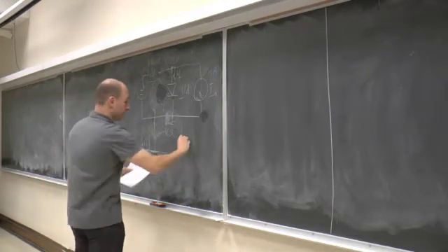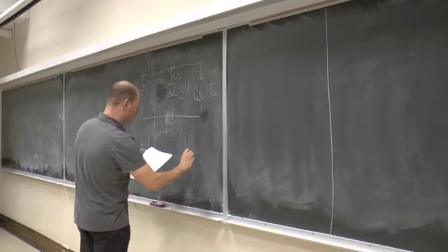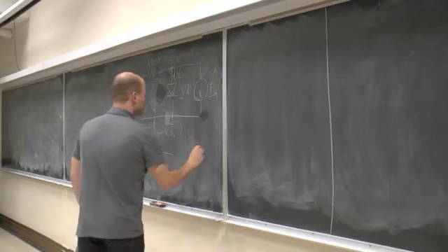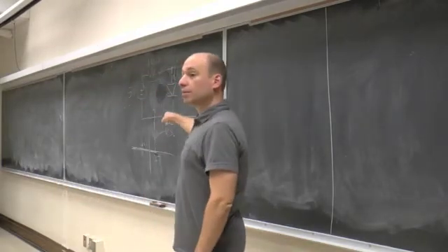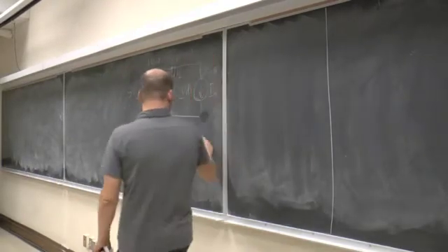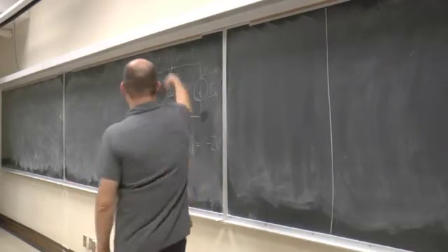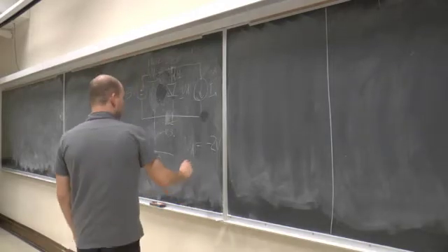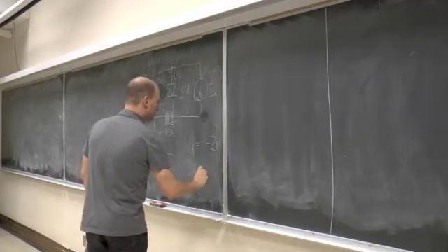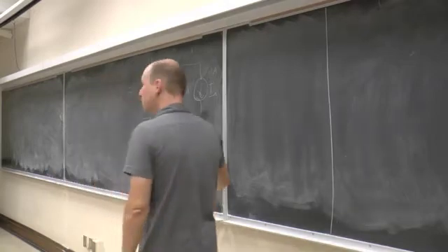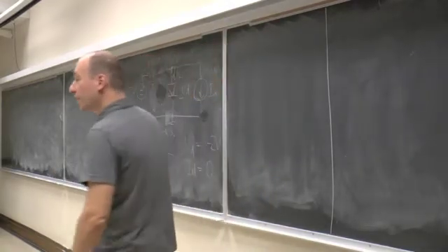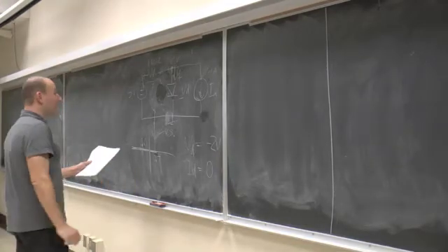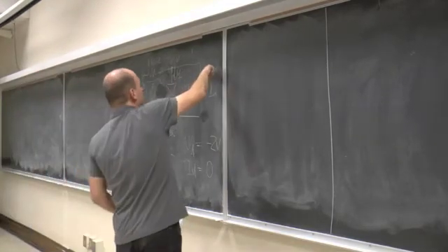Okay, so what's diode voltage? What's the voltage across the diode? That's what's being asked. -2 volts. And what's the current through the diode? Voltage across, current through. The current through the diode is indeed 0. We don't need to give units to the 0, but we can. Okay? All right. So, what about when the current is 4 milliamps?